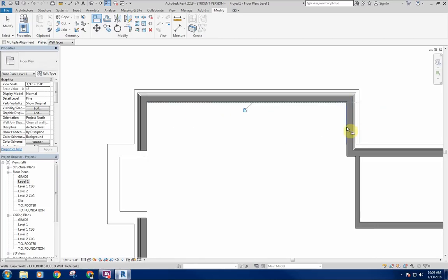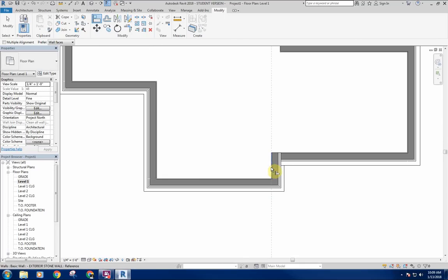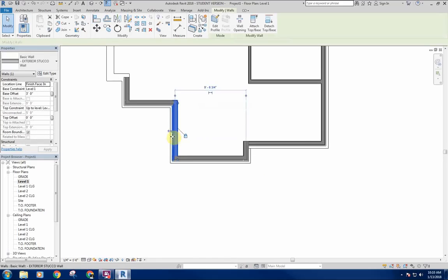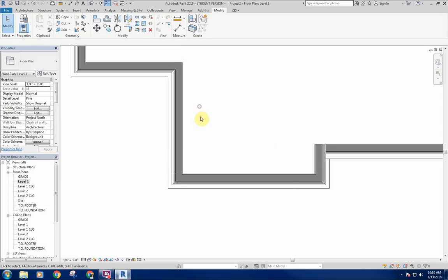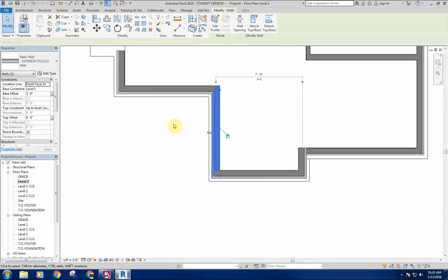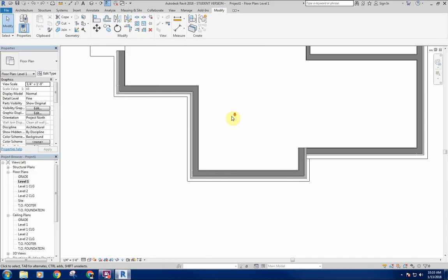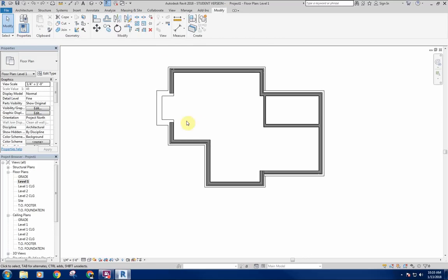That way I know that all of that is going to work exactly how I want it to in the future. The only way that I could possibly move these independently now is if I click that lock off. Then it wouldn't work. So now you can see this is my stone wall below, this is my stucco wall above. If I click and drag this, both of them move. And that's what I'm after. I want both of those to work together basically as one stacked wall.